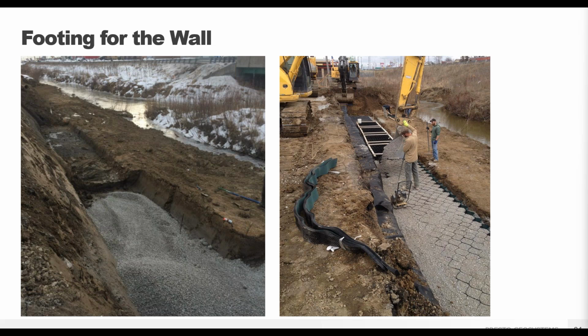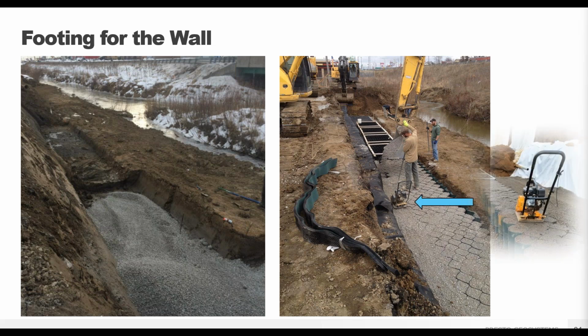Preparing the footing for the GeoWeb wall, and on the right, you see the footing layer of GeoWeb installed with granular infill placed, and we see the stretcher frames and infill process. A pro tip is to have a portable compactor on level with the build and compact as you go.